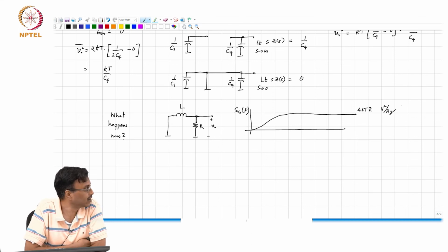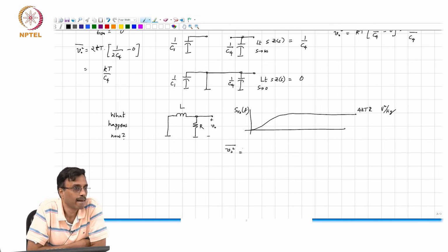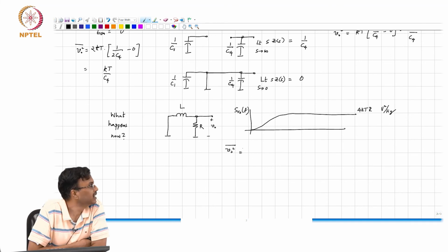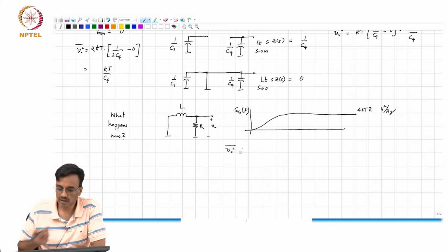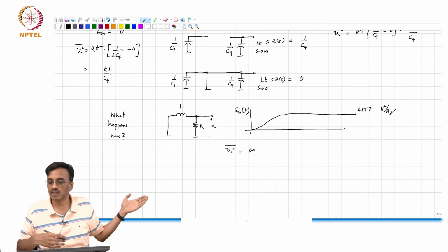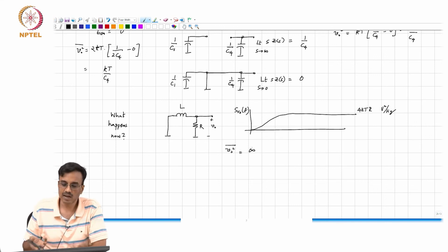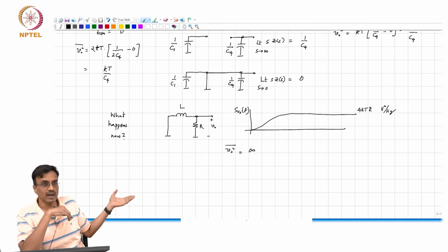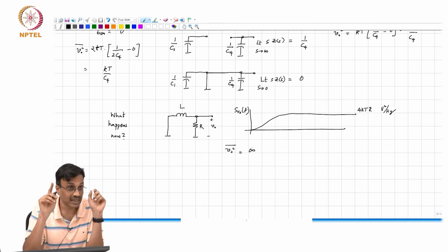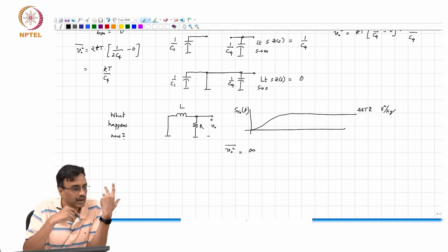So, what comment can we make about the total integrated mean square noise? It is simply the integral of this noise spectral density, and what is this telling us? Oh well, this is evidently infinity, right, because that spectral density is constant and you keep integrating till infinite frequency. So, for networks of this kind, theoretically this integral does not converge, correct, okay.